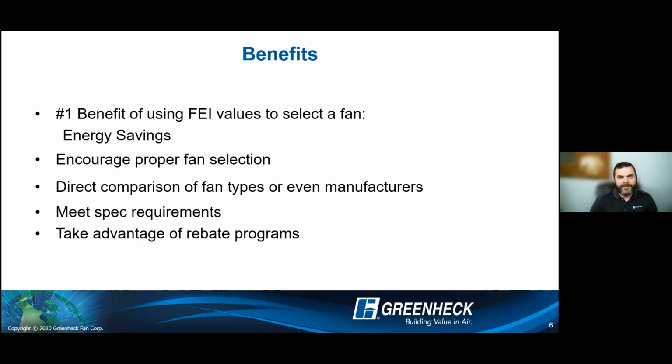And speaking of rebate programs, I'm not sure of your specific areas, but I have heard of parts of Michigan, Minnesota, Indiana, South Carolina, Colorado, Oregon. I mean, there are organizations that will have rebate programs that define, hey, if it's this type of fan, say it's an inline fan, and you're operating at 1.2 FEI or better, you are now capable of benefiting from this rebate program.